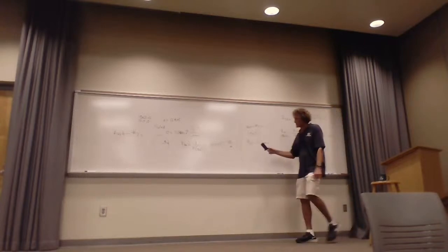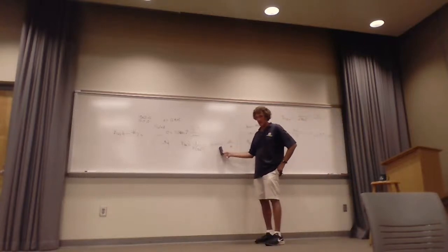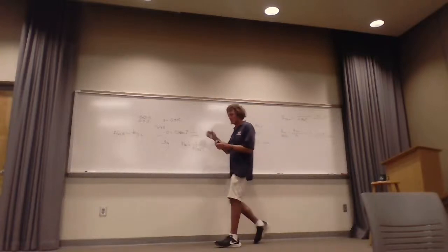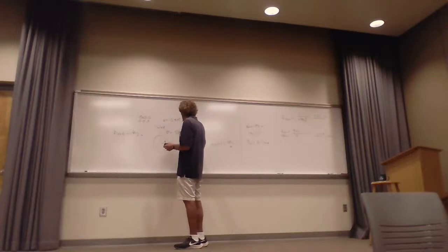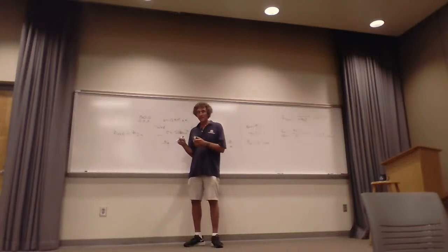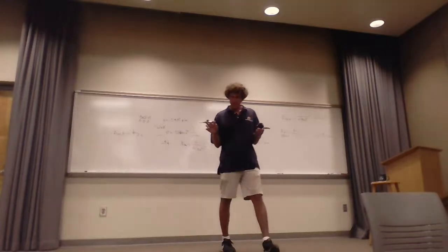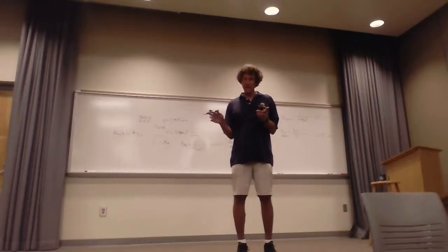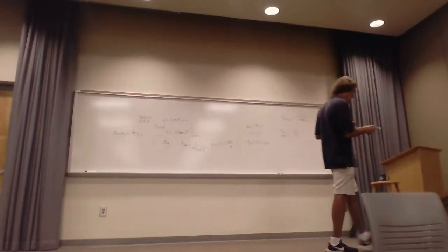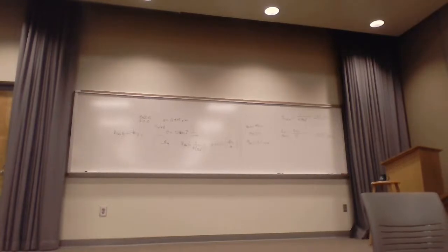So now forget that one. The solid one is what we calculated earlier, right? For the solid one, what do they have? They have 1.31 milliohms per meter. Then something is amiss. That means the radius there, this is millimeters, isn't it? Yes. According to the table, that is radius in millimeters. There's something wacky here.